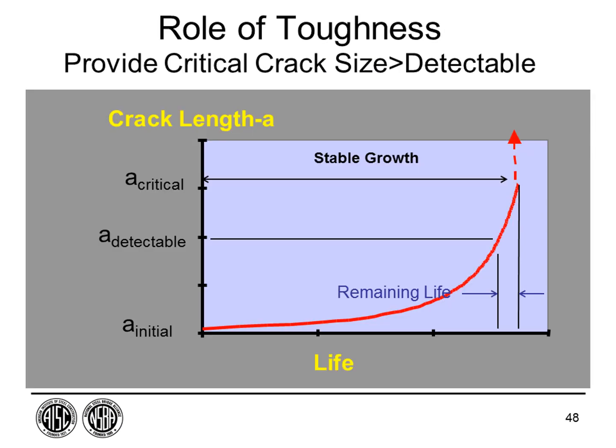Now what we're trying to do with this toughness is, if this is crack length here and this is time going this way, if it's a fatigue loading, the crack will extend with time. And if we inspect it, well, there'll be some detectable flaw size. And what we want to make sure is, before it reaches its critical flaw size, we're able to find it.